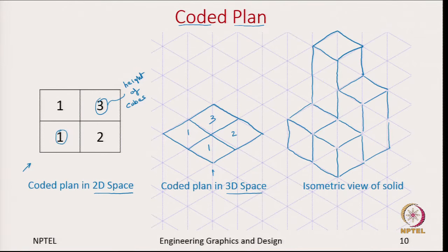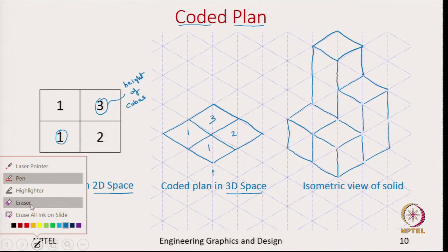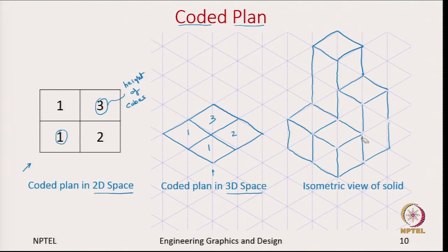But as you notice we have one principle. The principle is we only show lines when it meets 2 different surfaces. So, let us look at one by one and see where the extra lines are that we need to remove. So, for example, this vertical line here shares only one surface. Since there are no 2 surfaces meeting, we have to remove this line. Similarly, this line can be removed because this is all one single surface. The same with this vertical line here and the same here too.